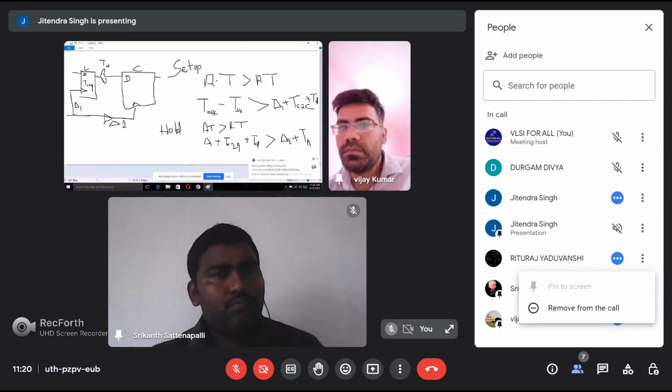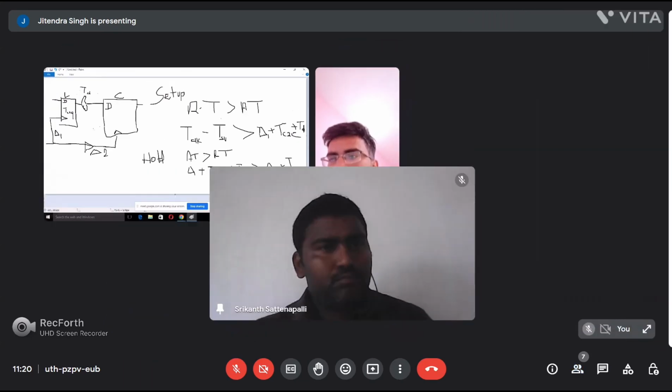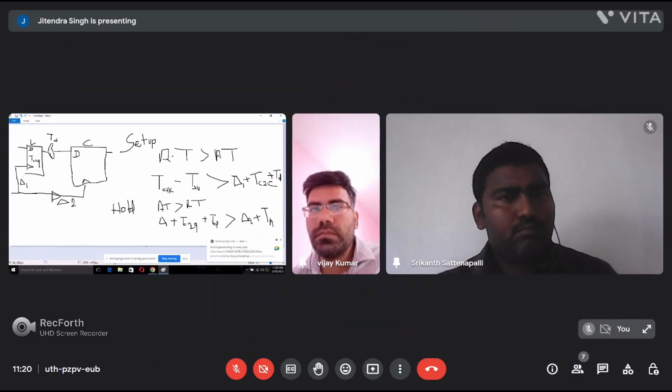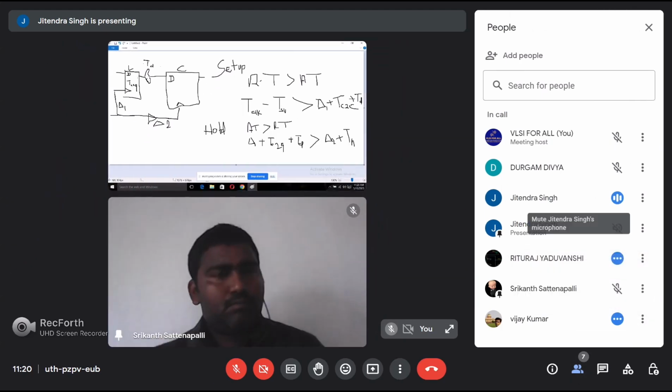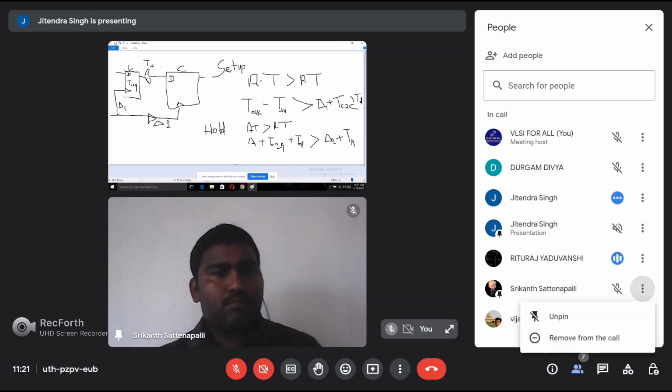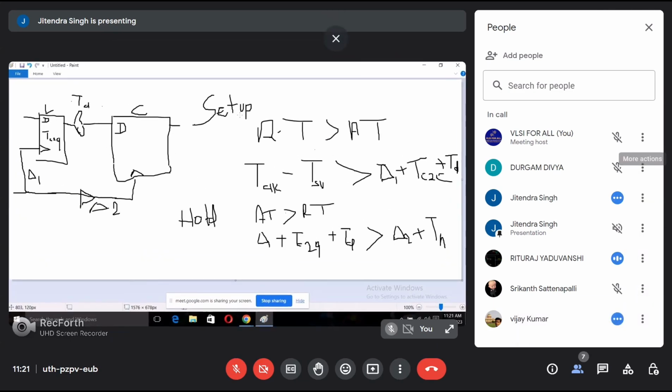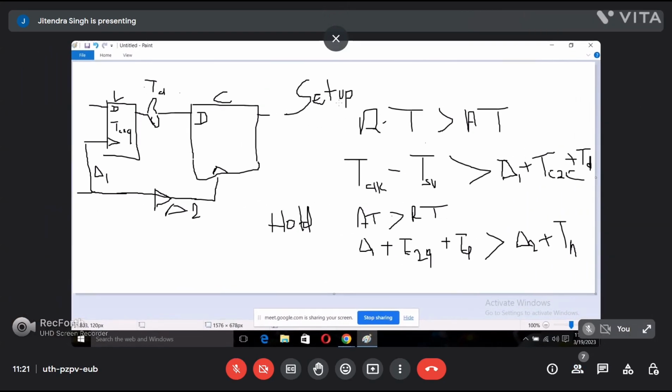Good. So I have taken two flip flops, a launch flip flop and a capture flip flop. I take the clock path delays, delta 1 and delta 2 here, and I take the clock to Q delay for this launch flip flop, and I take some combinational delay. Okay.